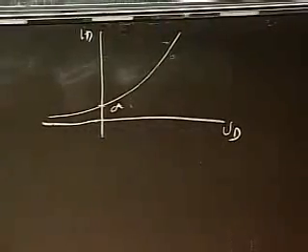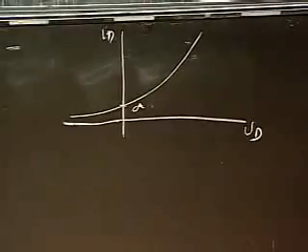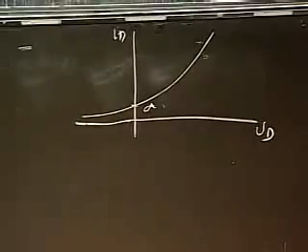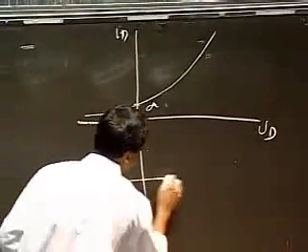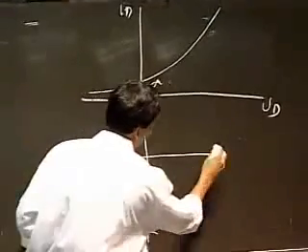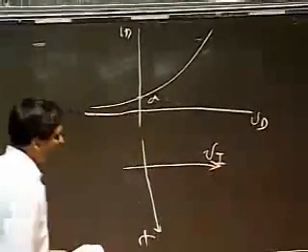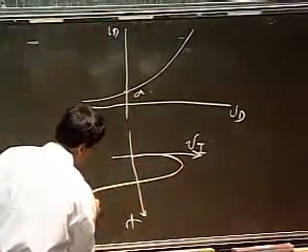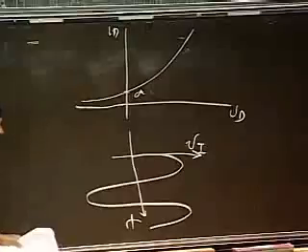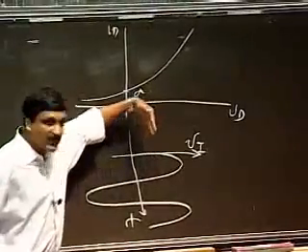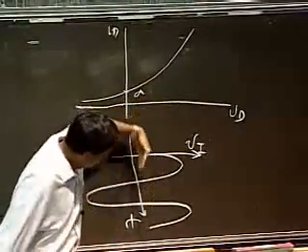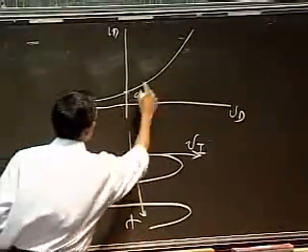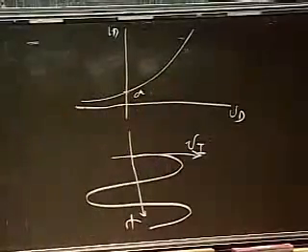And what I'm going to plot for you is, if I have a time-varying VD voltage, I just want to see what the time-varying ID current looks like. And a trick to plot that is to take your input voltage like so. And let's say I apply a sinusoid. So I'm just taking a time-varying sinusoidal voltage and plotting it, just rotating the plot 90 degrees like so. So I can see where these points correspond to on that curve.